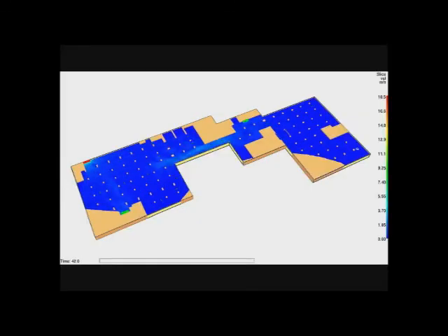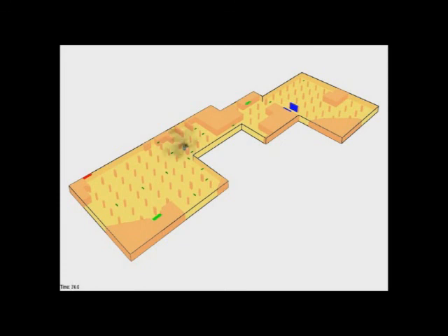So here you see the velocity results, how the velocities are developed. This is just with the exhaust fan and the fresh air fan working. So this is how the smoke is. Now when the jet fan starts, this is how the velocity is developed inside the car park, with time. And in this case, if a fire occurs, this is how the smoke will move.